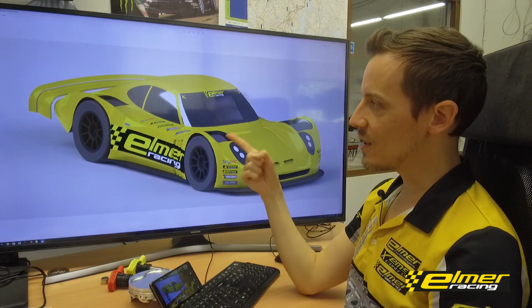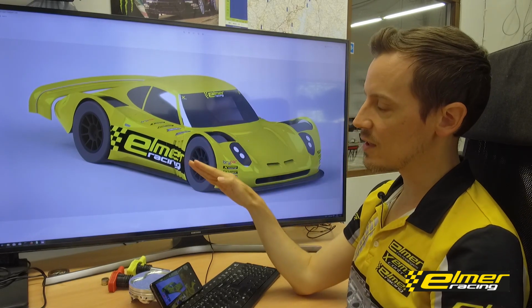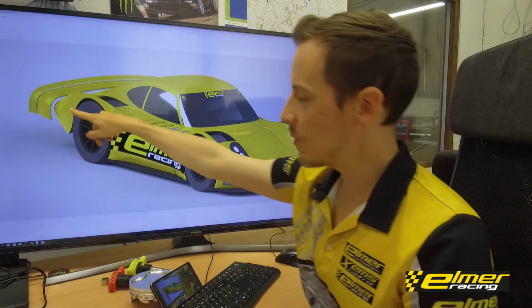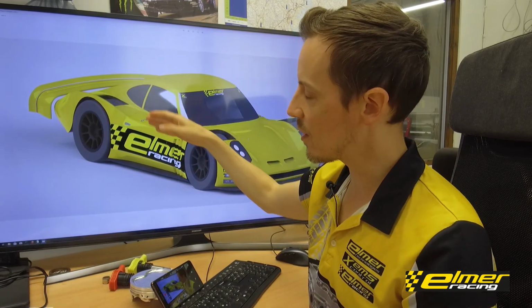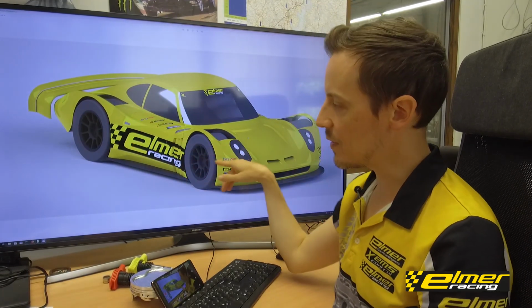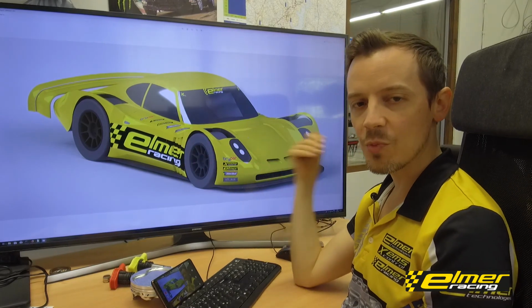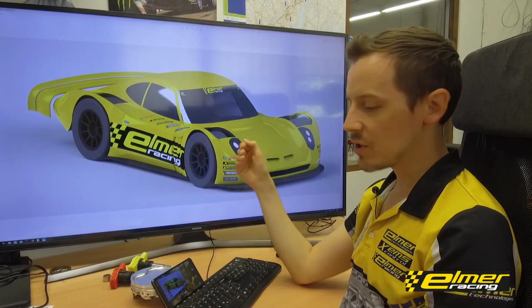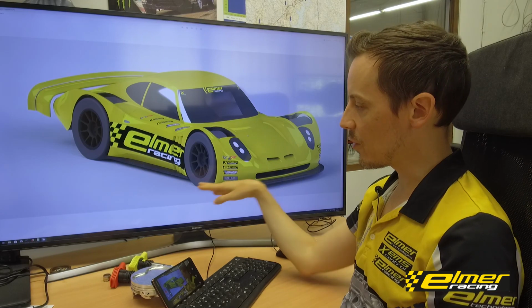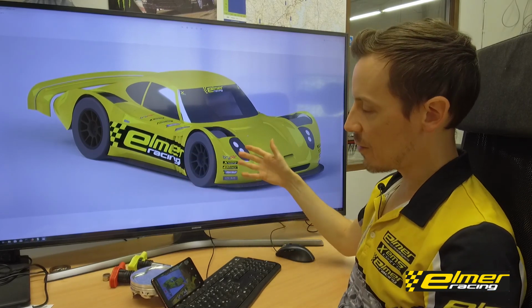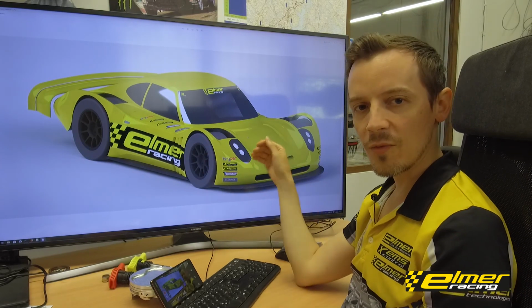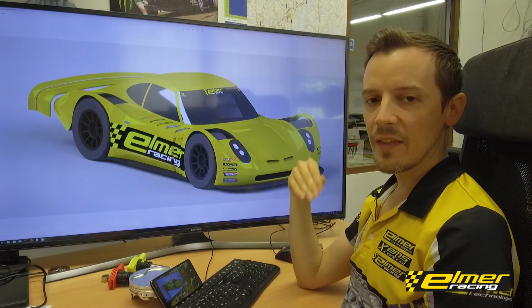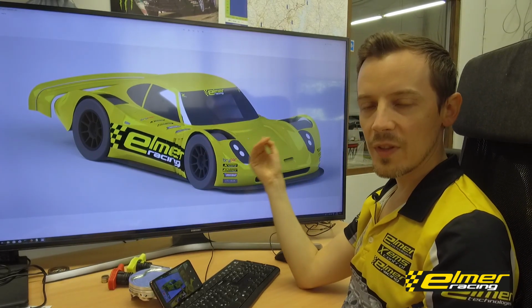And what we're interested in here is that because you get a higher flow velocity underneath the wing, we can increase the stream velocity around the rear of the car. Coupling that with the ground effect, you can get a much more effective suction behind the car. Depending on how you have your ground effect set up, you can create much higher flow velocities underneath the car, which again reduces the pressure there.